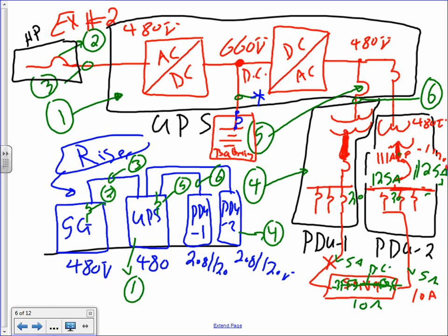Any question about the UPS? Like I said, when we go to Allianz, guys, you're going to walk into a data center and you're going to be looking at all these servers, racks of servers plugged into two outlets like this. And then these are going through PDUs. You can see the PDUs on the walls, against the walls, and the PDUs are tied to a UPS system, and the UPS system is tied to a battery, and the whole system is fed from a feeder from the switchgear. Any comments, any questions? That's as beautiful as it can get in the electrical industry.